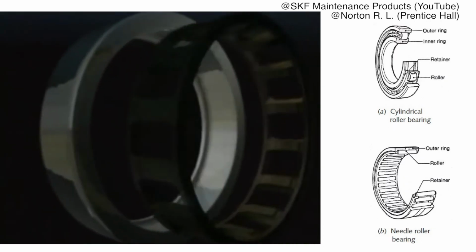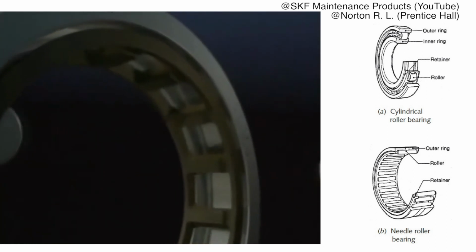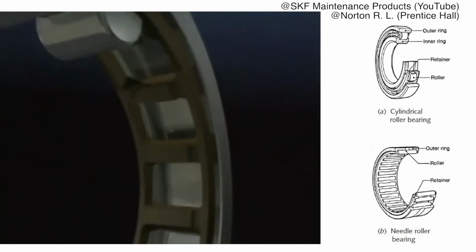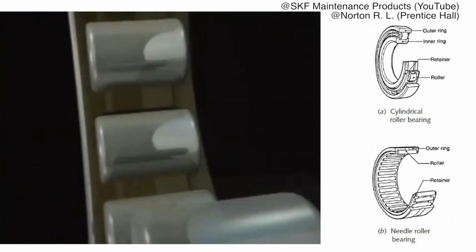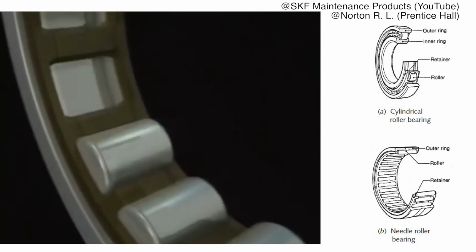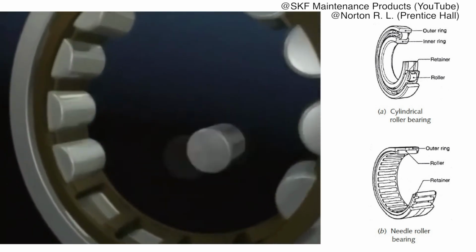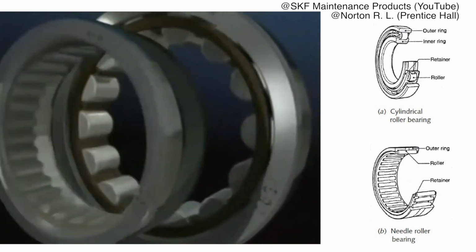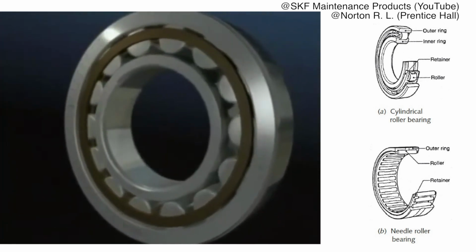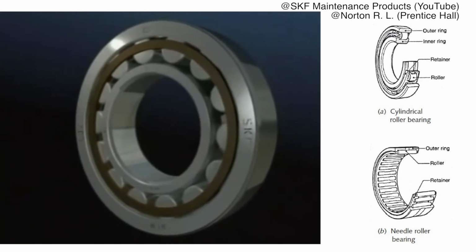A straight roller bearing utilizes a cylinder instead of a ball as the roller. The contact with the inner and outer races in a straight roller bearing is a line rather than a point. Thus, it can handle larger radial loads than a ball bearing. Straight roller bearings are not designed to handle thrust loads. They require almost perfect geometry of the raceways and rollers. A slight misalignment causes the rollers to skew and thus may ruin the bearing.